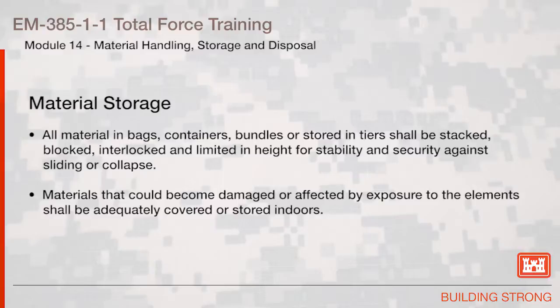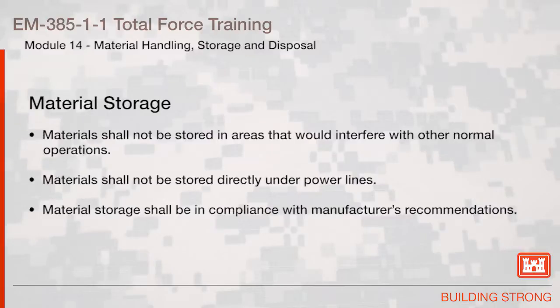All material in bags, containers, bundles, or stored in tiers shall be stacked, blocked, interlocked, and limited in height for stability and security against sliding or collapse. Materials that could become damaged or affected by exposure to the elements shall be adequately covered or stored indoors. Materials shall not be stored in areas that would interfere with other normal operations. Materials shall not be stored directly under power lines. Material storage shall be in compliance with the manufacturer's recommendations.